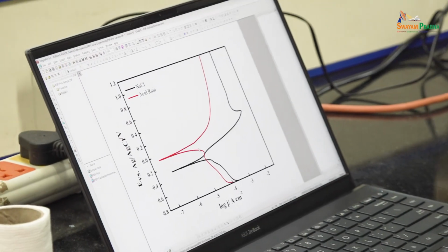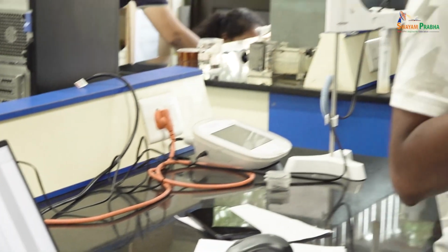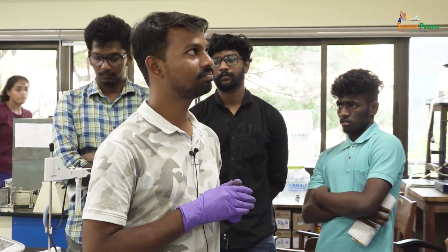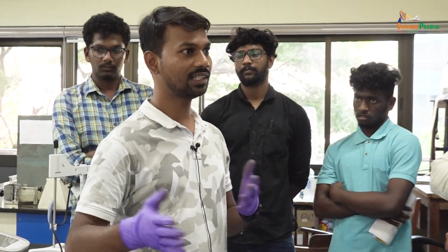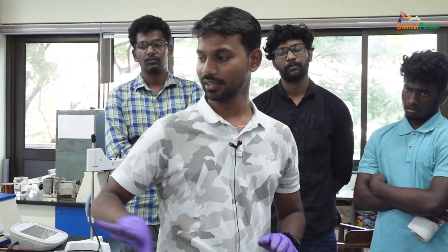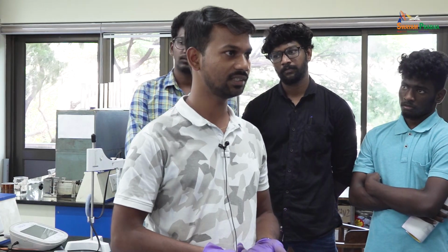The acid rain solution does not have a fixed composition, as it varies with the regions of the world. There is nothing more to tell. We will draw the tangents, determine E-corr and I-corr in both conditions, and conclude which is corroding more.